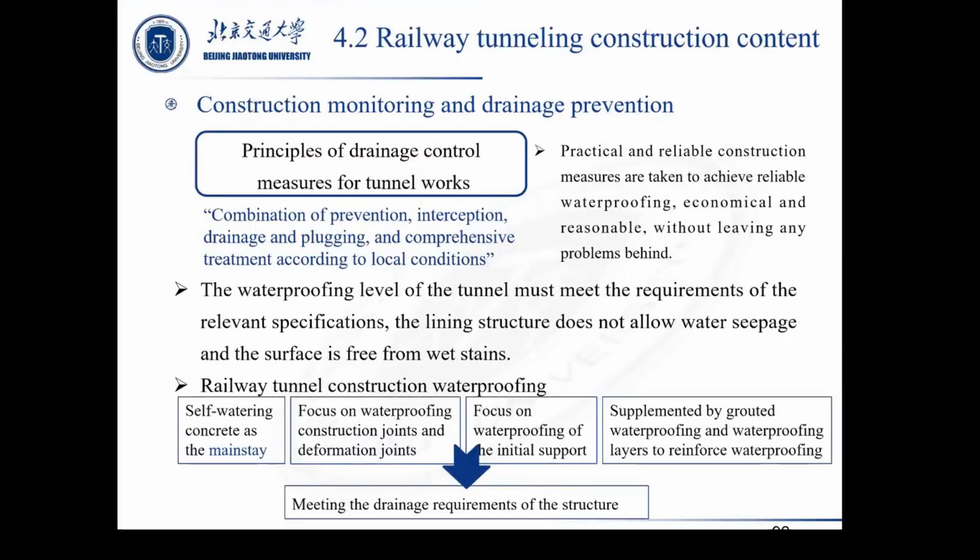Lining structure does not allow water seepage, and the surface is not allowed to have a stream. Tunnel construction waterproofing takes concrete as the main body. Deformation joint waterproofing is a focus, and pay attention to the initial support waterproofing supply from the back.